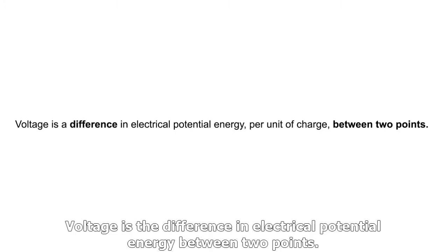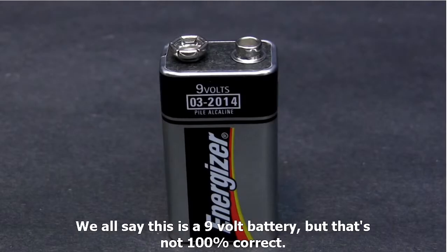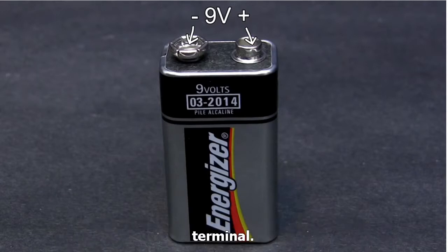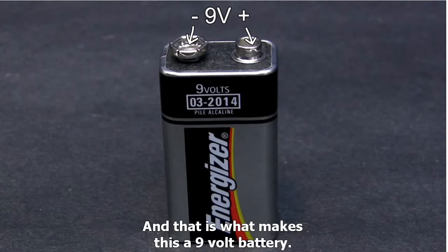Voltage is the difference in electrical potential energy between 2 points. In other words, voltage is always relative. We all say this is a 9-volt battery, but that's not 100% correct. What we're supposed to say is that there's an electrical potential difference of 9 volts between this negative terminal and this positive terminal. There's a difference of 9 joules for every coulomb that flows out of the battery, and that's what makes this a 9-volt battery.